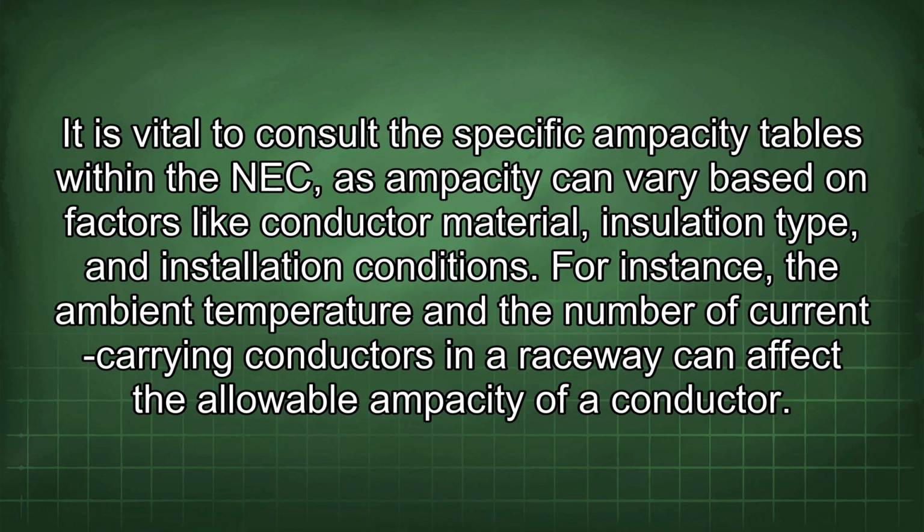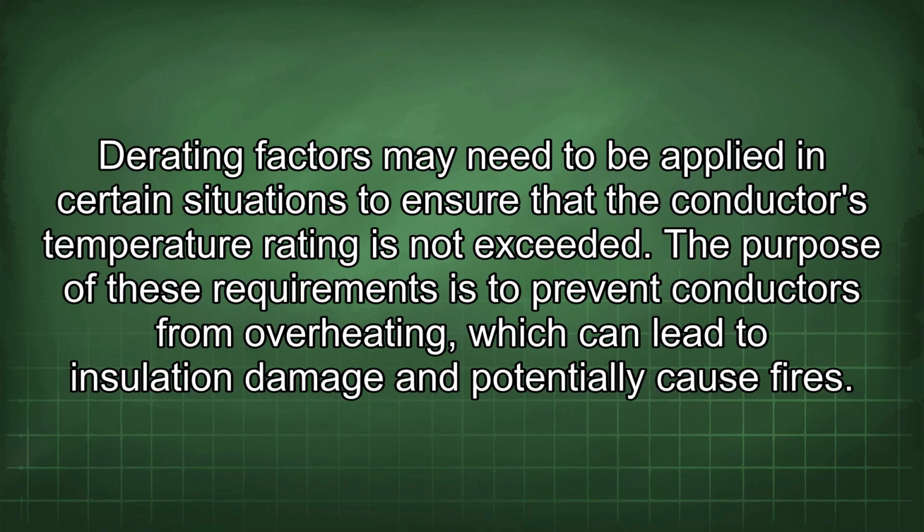It is vital to consult the specific ampacity tables within the NEC, as ampacity can vary based on factors like conductor material, insulation type, and installation conditions. For instance, the ambient temperature and the number of current-carrying conductors in a raceway can affect the allowable ampacity of a conductor. Derating factors may need to be applied in certain situations to ensure that the conductor's temperature rating is